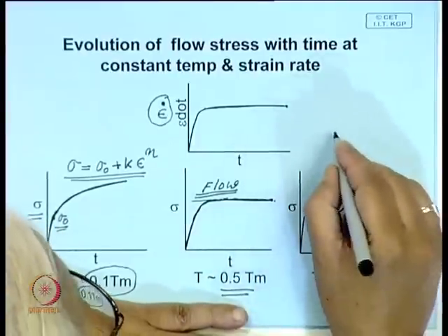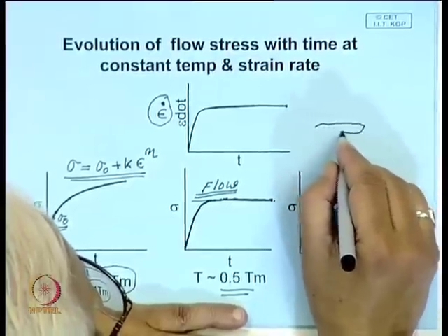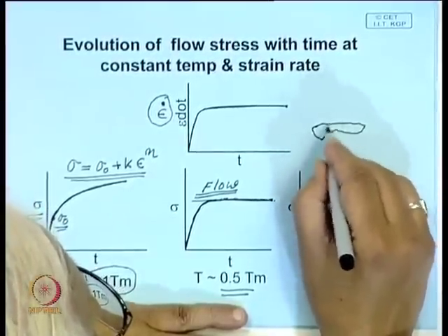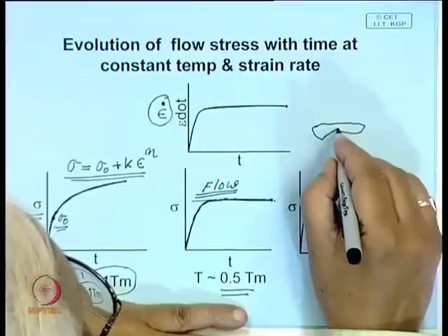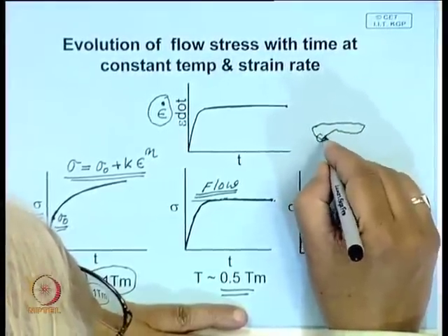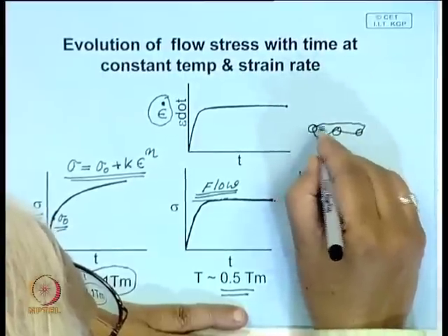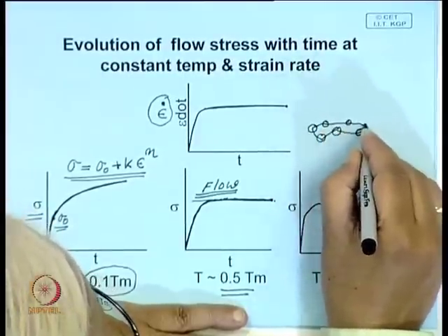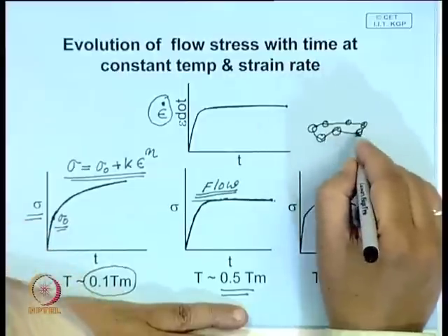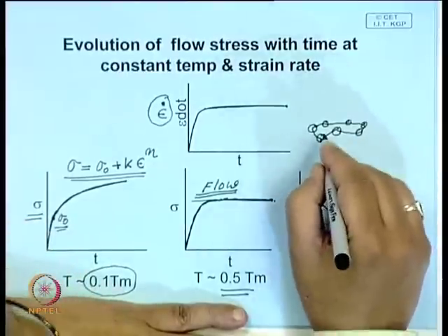And in the other case, where the material behavior is such that the energy in the deformed grain exceeds a critical energy, recrystallization starts. Strain free grains nucleate at the grain boundary and keep on growing, and when these strain free grains develop, their strength is low.